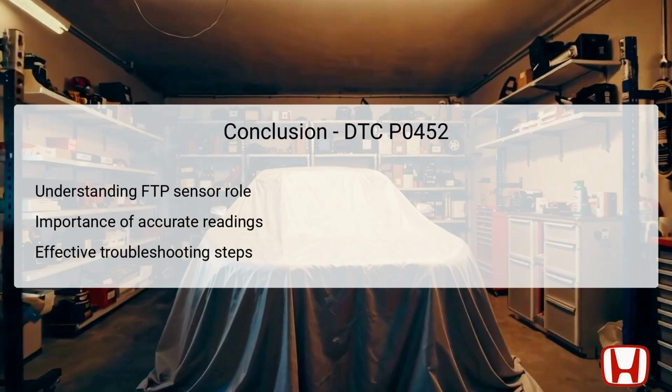In conclusion, understanding the role of the fuel tank pressure FTP sensor is vital for effective diagnosis and repair related to DTC P0452. This DTC indicates low voltage in the FTP sensor circuit, making it essential to ensure accurate readings for proper engine management and emissions control.